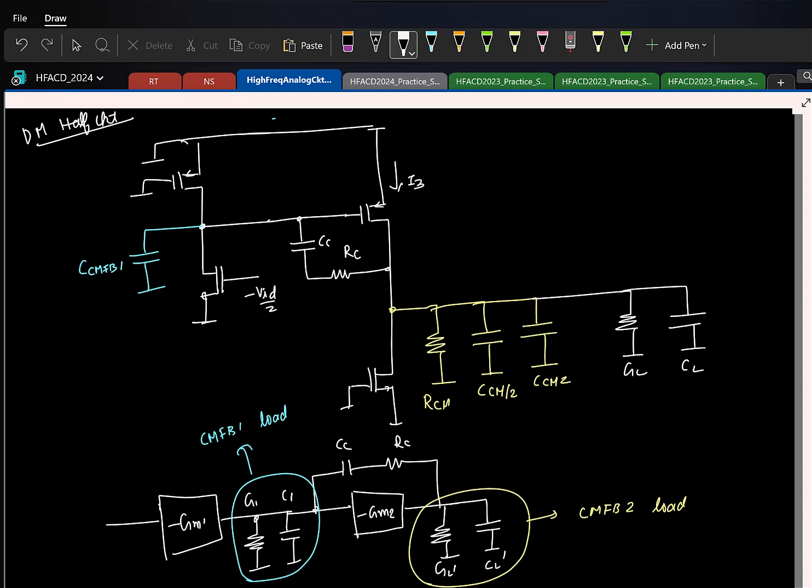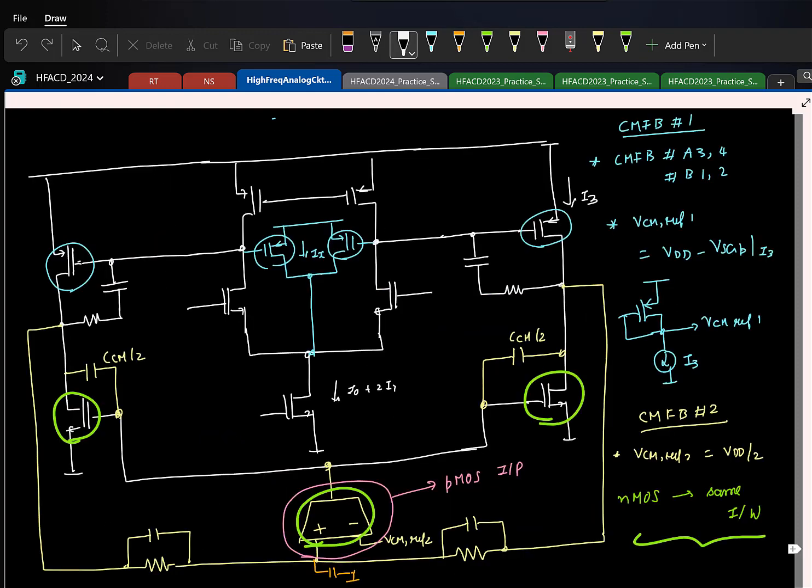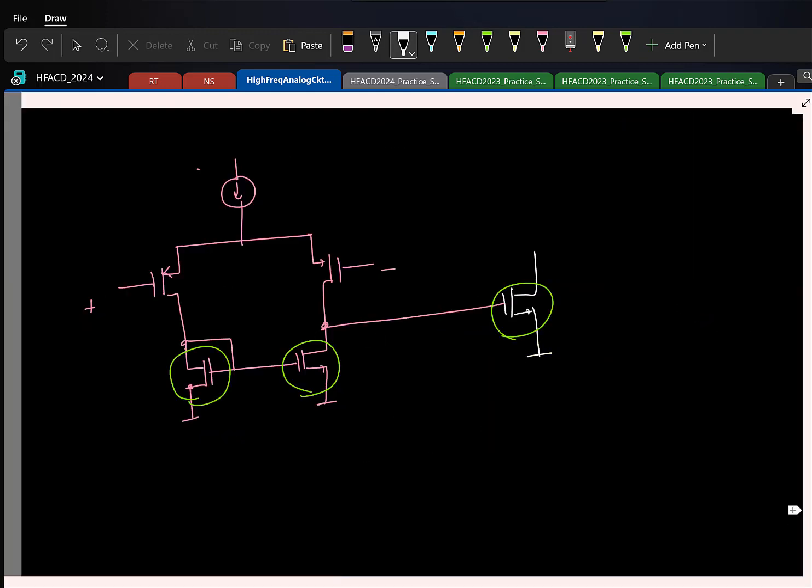Great. So now of course we'll know from your specifications you can find what is the omega u for the differential mode and your phase margin for your differential mode. Right. And similarly now you also see that we also have a negative feedback loop working separately for setting the common mode, and you can see here.